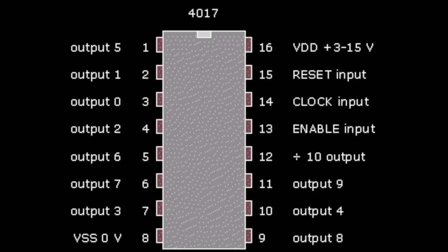In the full counting circuit, we will wire the divide by 10 pin to the clock input of the binary up and down counter, which will also decrease the speed of the counter since the clock signal now needs to produce 5 highs before the value increases in binary.